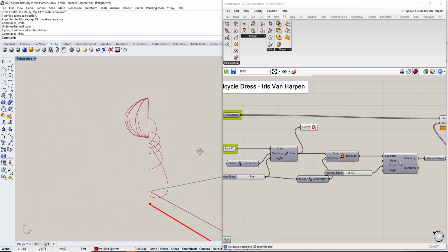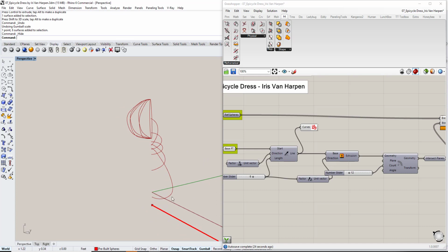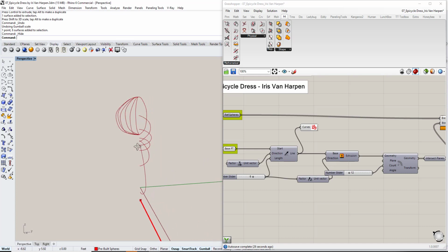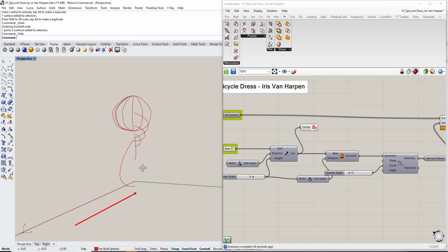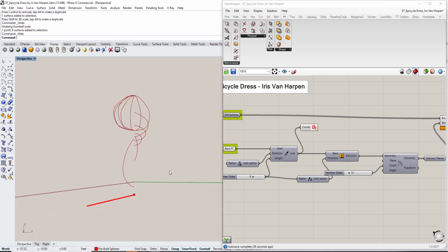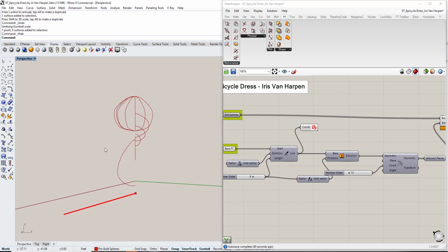And you can see that it started at the bottom, and one of the planes intersected the bottom sphere. Then the next plane intersected the next sphere, and so on. I don't want it to go this way. I don't want to start at the bottom and move up. I want it to stay on the bottom one, finish intersecting with all of the planes, then move to the next one, finish intersecting all of the planes, then the next one, then the next one, and so on. So when you want to do that, whenever you want to hold the geometry and complete a task, you want to make that geometry its own list.